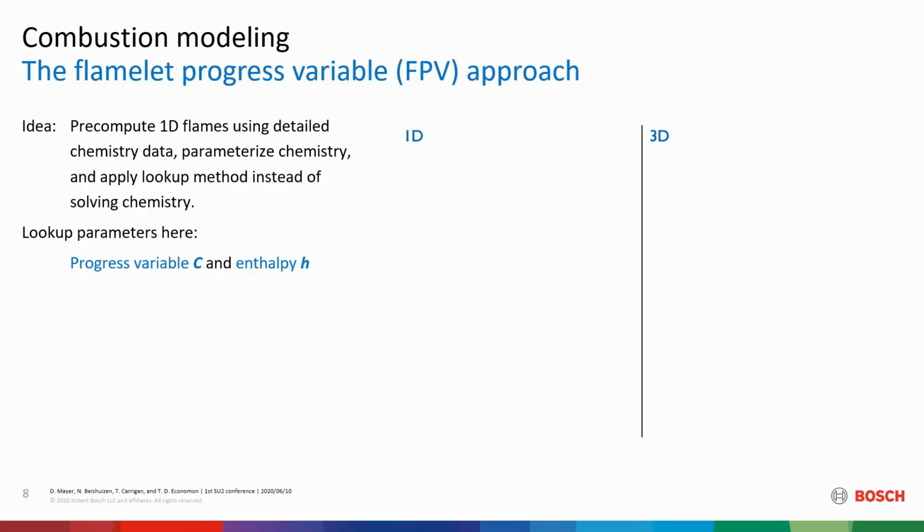The enthalpy is used as a second coordinate to model heat loss effects that we encounter very much in the heat exchanger. And because the total enthalpy that we use here is not a function of the local gas composition, in our case we have two orthogonal coordinates in that space, which gives this model very nice mathematical properties.